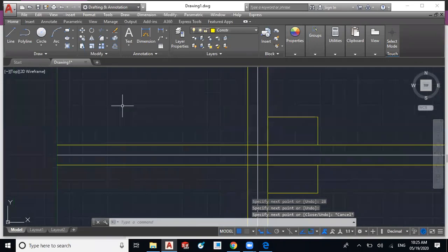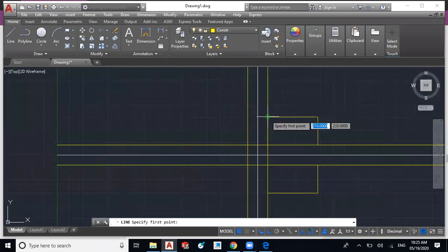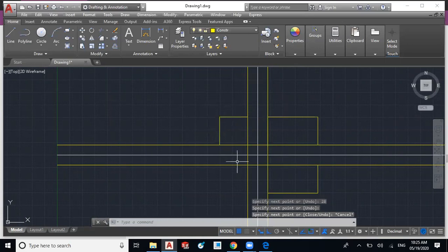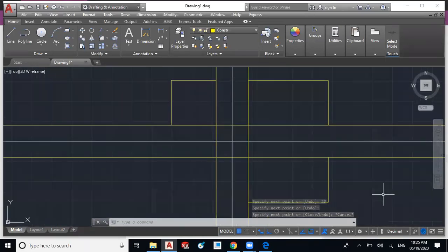Now we have to draw the box for side view. So track this height point. So you have to track it on this spacing line. Draw from this, the width is 28, and drag down at perpendicular point. So we have constructed three boxes for front, top and side view. So in these boxes we have to draw the views by using outline and hidden lines.